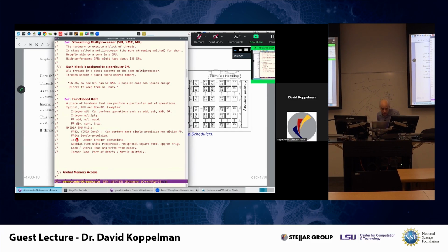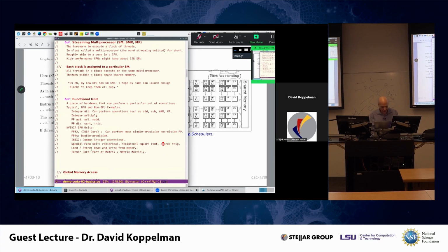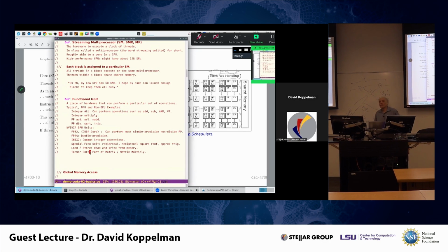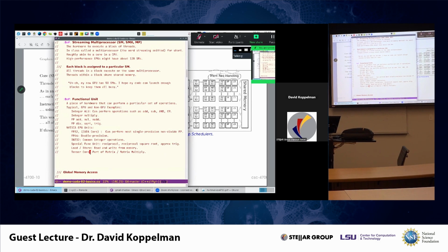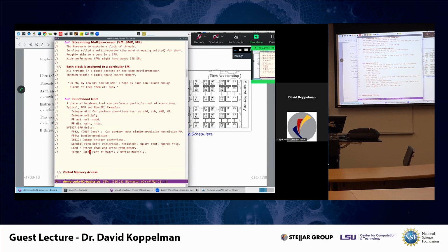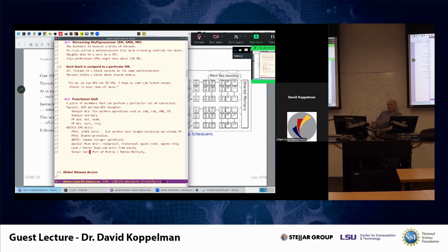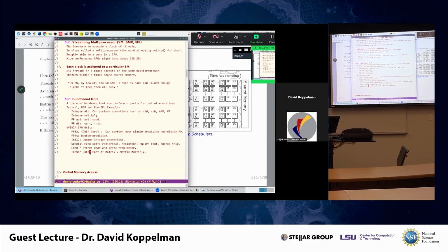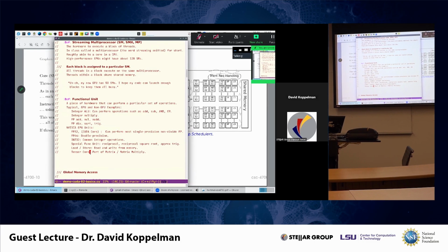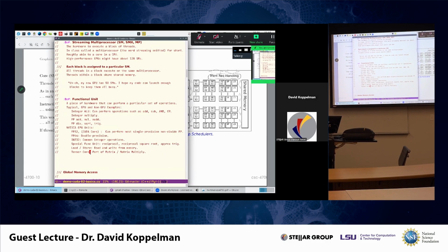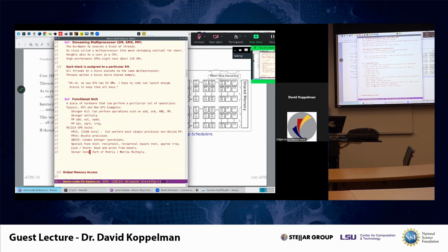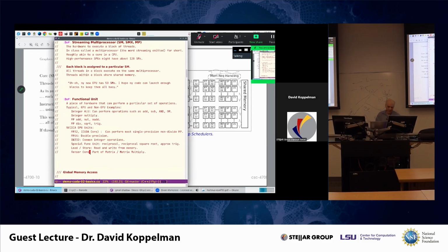All right, also the SFU, special functional unit, as I said, does reciprocal square root, and some trigonometry. Load stores for accessing memory. Tensor cores, what these do are matrix operations. Now, there's not a single matrix multiplication. They're done in pieces. But what makes the tensor core special is that unlike the other operations, when you operate a tensor core instruction, you definitely are having all the threads in a warp participate. So the data for a matrix comes from all of the threads in the warp, in contrast to other instructions where it's individual to a thread.